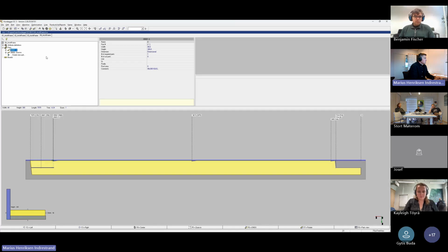So by opening this in SpeedCut, we can see the one with V-cut will be 4 minutes and 24 seconds. Using the groove tool, there will be 5 minutes and 38 seconds. So it's 3 grooves, so it's approximately 25 extra seconds on each, or 1 minute and 14 seconds to produce a somewhat similar beam. So these are pretty similar.